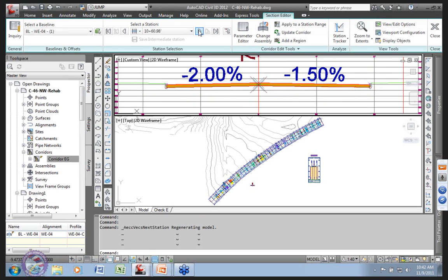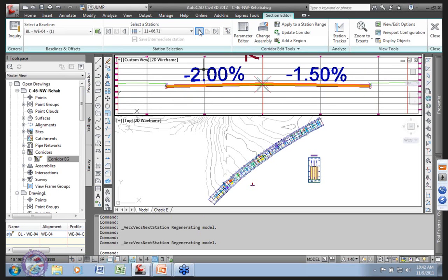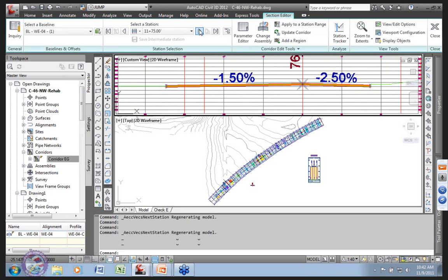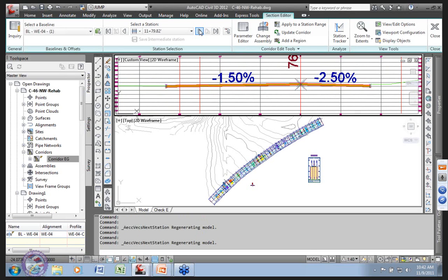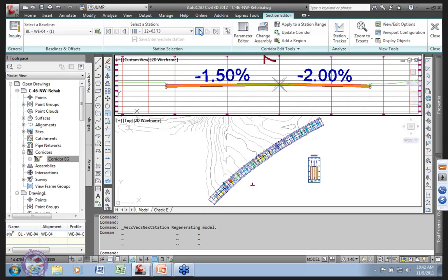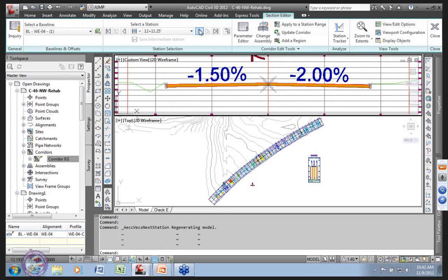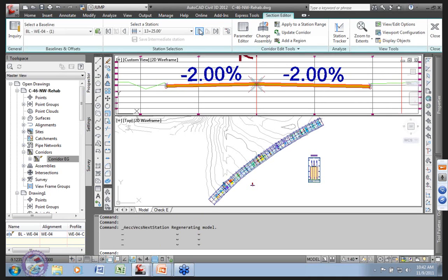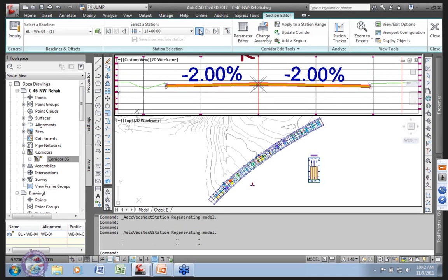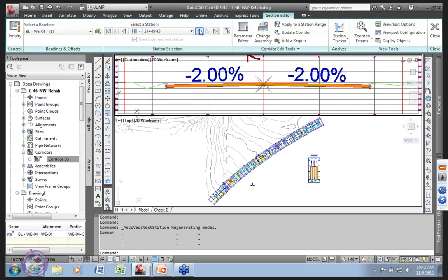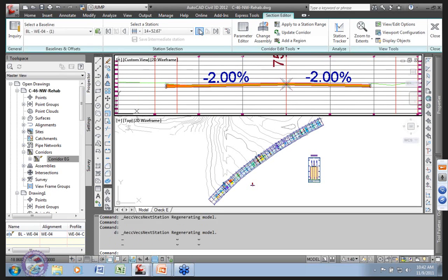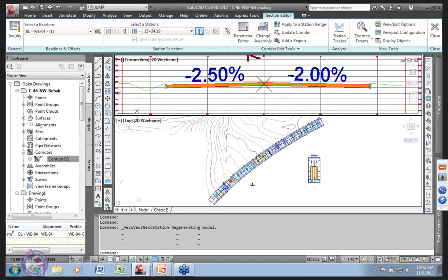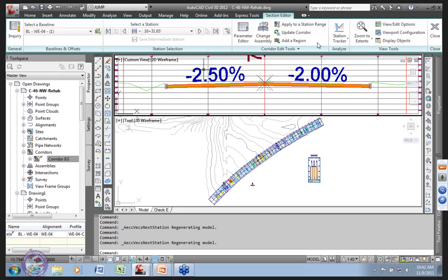Okay, and we can hop around and you'll see, hey, I get a nicely resolving 2%, right? And even through my intersection, you can see, based on that, feature lines that were actually constructed by grabbing nodes of points that we had in our first drawing. All right, I get a pretty nice match to overlay right to the flow line, all the way up and down the street. Okay, adding and cutting and producing the result I need.